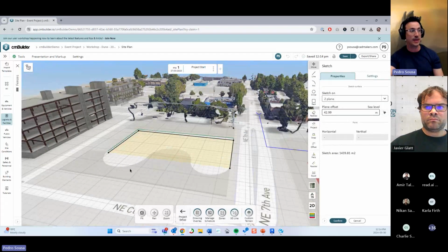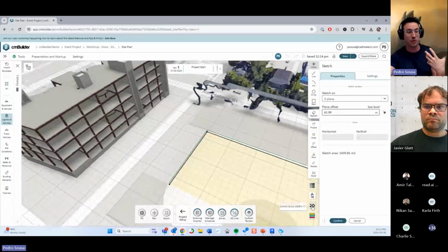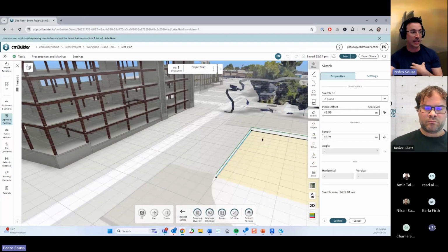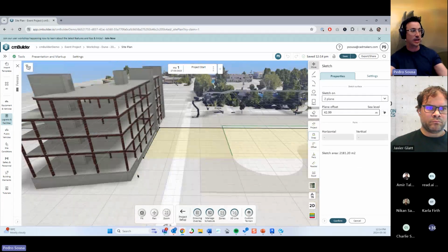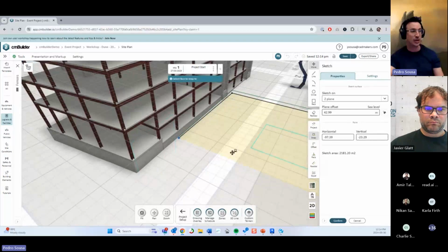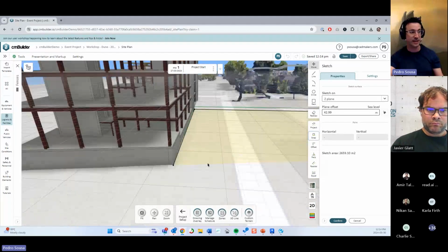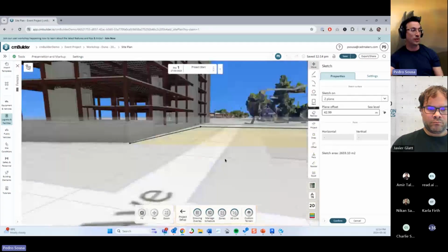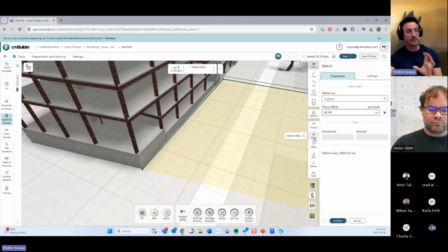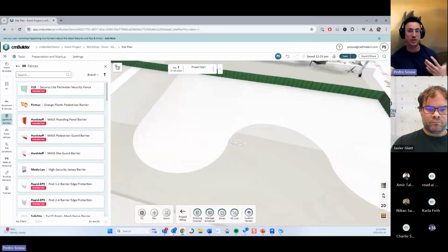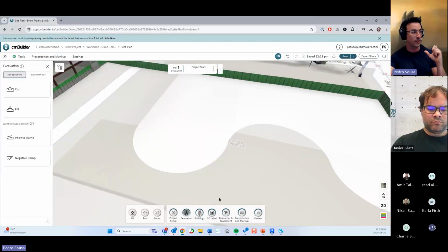The snapping feature over here works best if you're flipping through 2D and 3D, right? Because you are able to select a shape, click on snap, and say that you want that shape to be aligned with an existing face. So now that line over there is aligned with that, and that also applies to points. You can select a point and make it snap to a face, and the point will extend the line until it touches that face, until it's aligned with that face. The snapping tool is super interesting to use whenever you have excavations, for example, that you want to build aligned with other cuts.